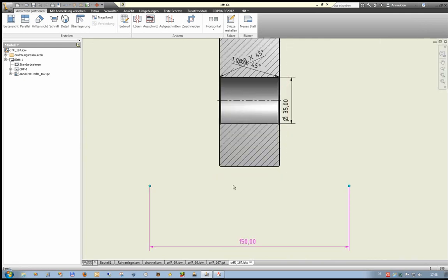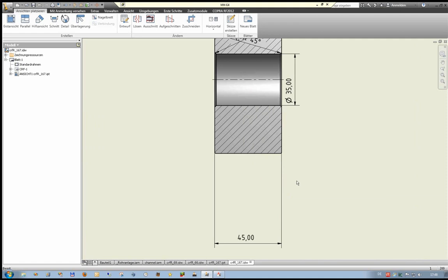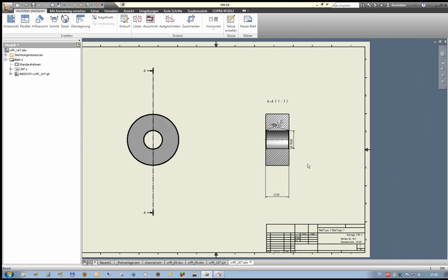Yeah, and the width. In this case, also Inventor has somehow lost information to where it is, but just put it there and it's fixed. Okay, the contour in this case, it's just a cylindrical roll, but usually if this is a contour, whatever, then you don't get any information or any dimensioning on the contour itself because we can't put them in the template. That's obvious. So in this case, you have to create these additional dimensions in the roll drawing.